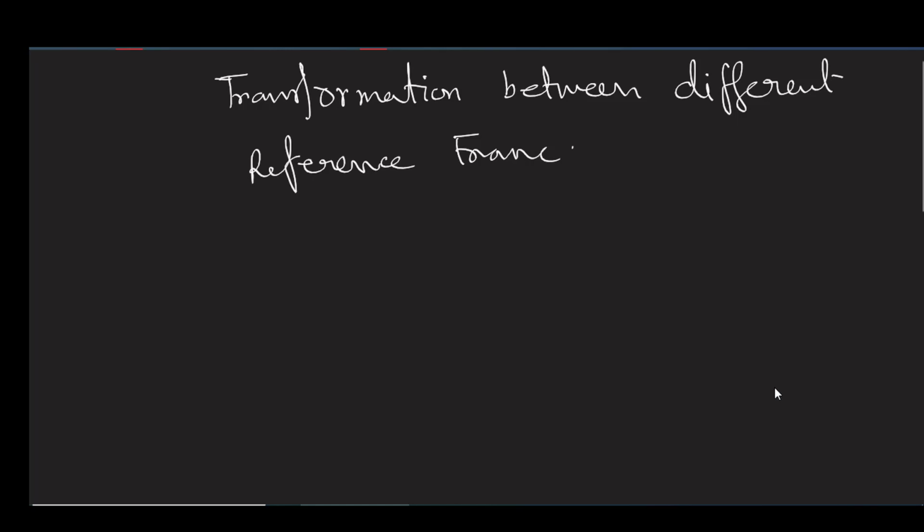In some derivation and analysis, we will find that it is convenient to relate the variables in one reference frame to the variable in another reference frame, and without involving the ABC variables in transformation. Now, what we are looking for typically is something like f of y, this is our new reference frame, q d naught s, a transformation matrix.